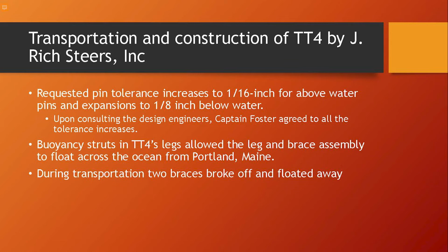While TT4 was being constructed on land, J. Rich Steers Inc. requested the Navy engineer to allow for pin tolerance increases. The design specified 1/64th inch tolerance, but they requested 1/16th inch for above water pins and 1/8 inch below water pins. Captain Foster, who oversaw the project from the Navy, approved all of these tolerance increases.